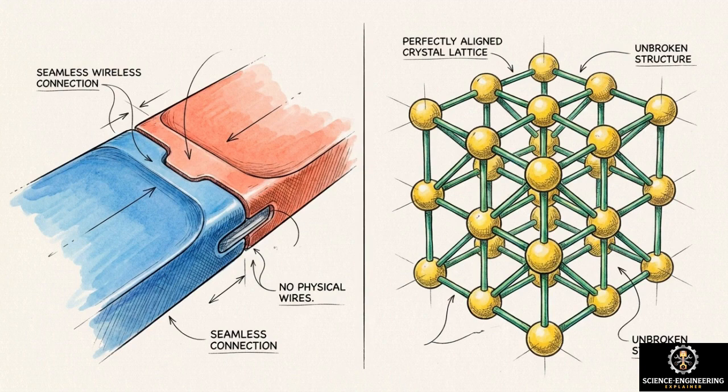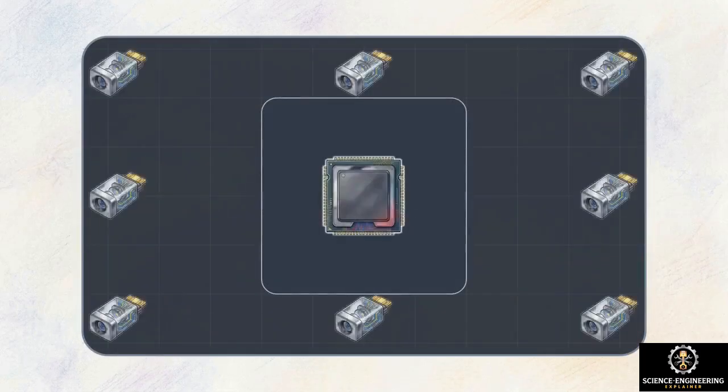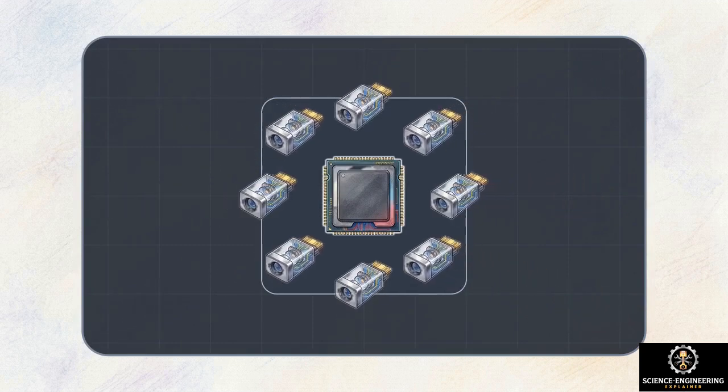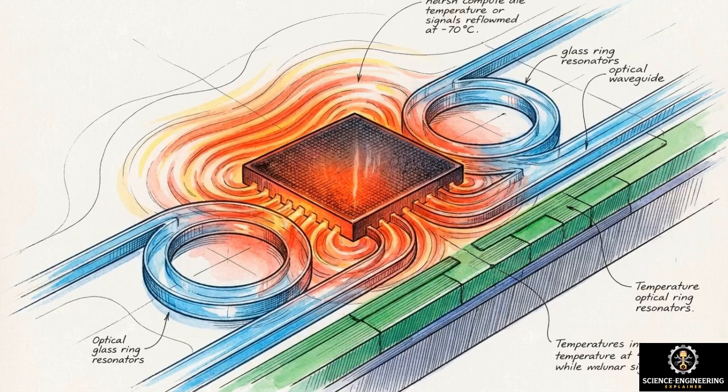The architectural goal driving these integration methods is the transition from pluggable transceivers to co-packaged optics. In a CPO architecture, high-density optical engines are relocated from the board's edge directly onto a shared package substrate with a high-power ASIC. This keeps the electrical traces short to prevent signal degradation, but placing signal-sensitive optical components next to a compute die creates significant thermal crosstalk.